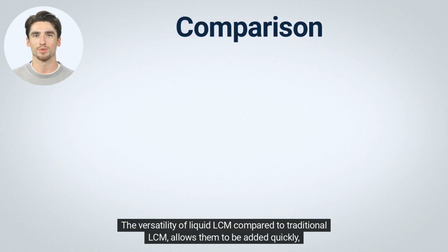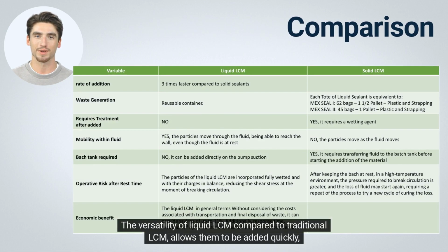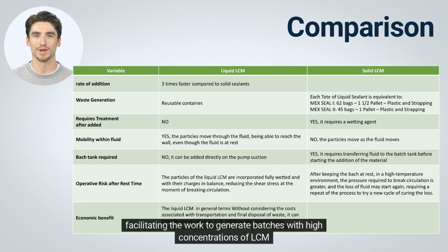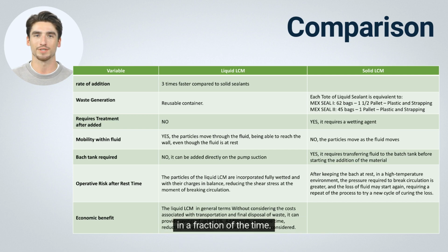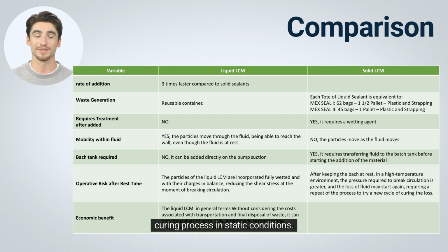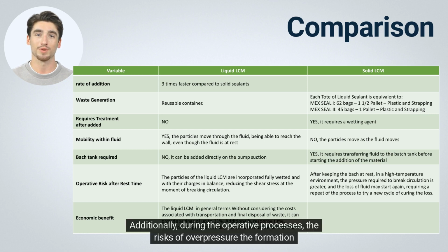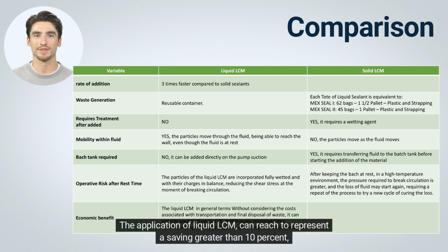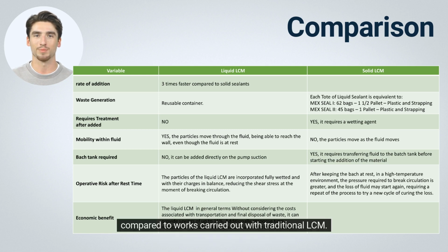The versatility of liquid LCM compared to traditional LCM allows it to be added quickly, facilitating the work to generate batches with high concentrations of LCM in a fraction of the time. On the other hand, the particles that are wetted previously improve their mobility, facilitating the formation curing process in static conditions. Additionally, during the operative processes, the risks of overpressuring the formation are reduced due to the thixotropy provided by the liquid LCM. The application of liquid LCM can represent a saving greater than 10% compared to works carried out with traditional LCM.